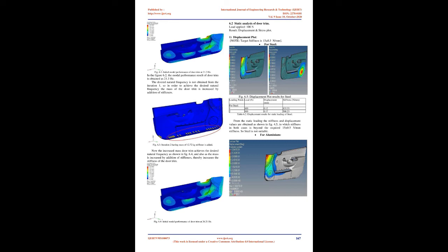5.2 Quality parameters considered while meshing the door trim. Warpage is applicable only to shell and hexahedron elements. In a shell element, if the third node is out of plane by a certain angle, error due to warpage can occur. In a hexahedron element, it deviates from the plane from the 3-node plane to the 4-node plane.